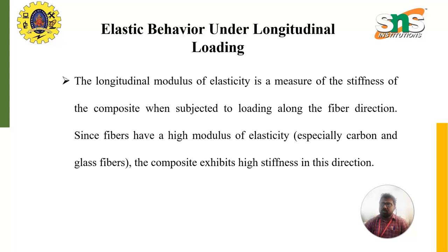The composite material has a higher stiffness than the matrix alone due to the strength and stiffness of the reinforcing fibers. The fibers carry the majority of the load, and the matrix material deforms less, acting primarily to transfer the load between the fibers.